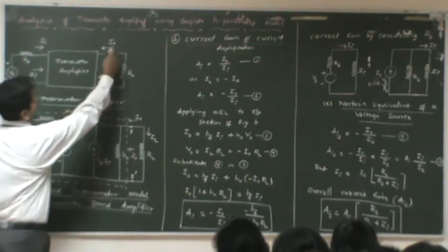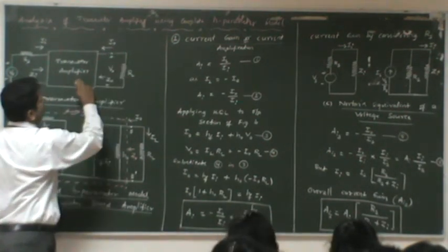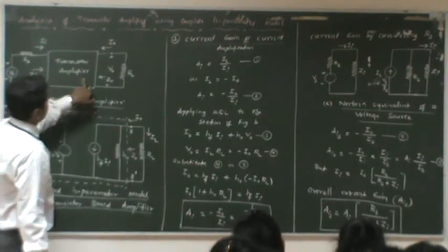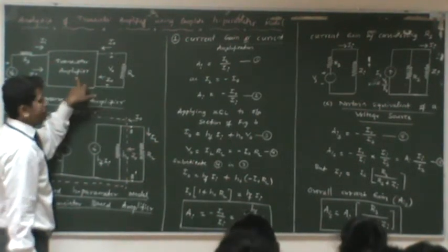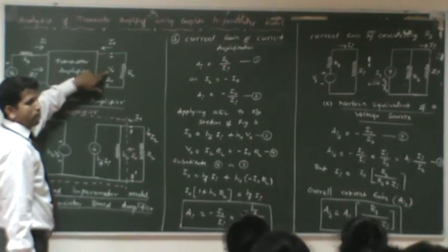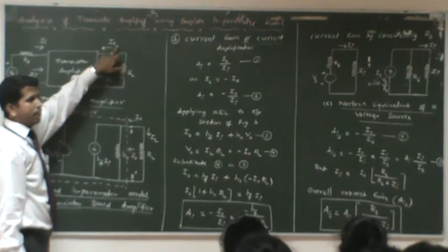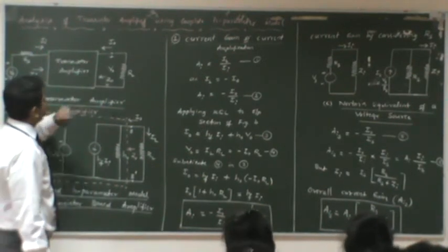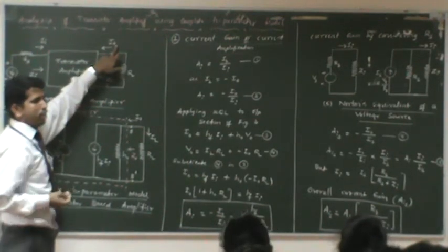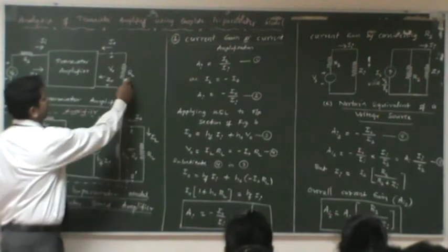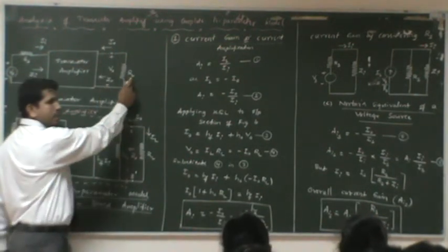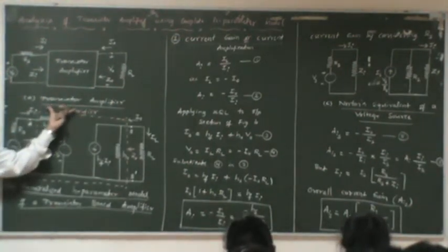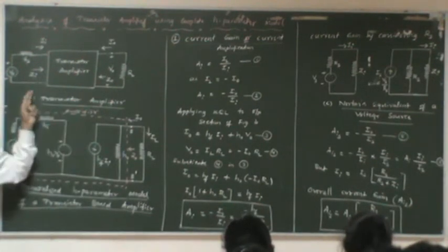Look at this, this is the current from the amplifier, which we indicate as I0, the output current, and the output voltage produced by the amplifier, which we label as V0. Do not worry about the directions of the currents I0 and IA. We only assume the directions here. Later on, they can change depending upon the current. Also, the amplified signal will be delivered to the load resistor, which is RL. So this is the transistor amplifier shown in terms of a block diagram.